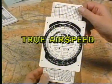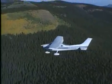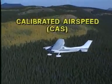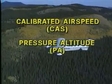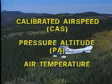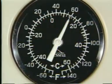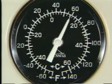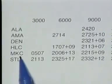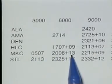You can also use this side of the computer to determine true airspeed. However, to do this, you must know 3 things: calibrated airspeed, pressure altitude, and air temperature. While in the air, you can determine the temperature by referring to your outside air temperature gauge. For pre-flight planning purposes, you can get the forecast temperature for your planned altitude from the winds and temperatures aloft forecast.